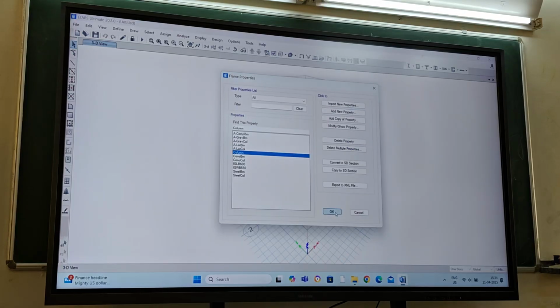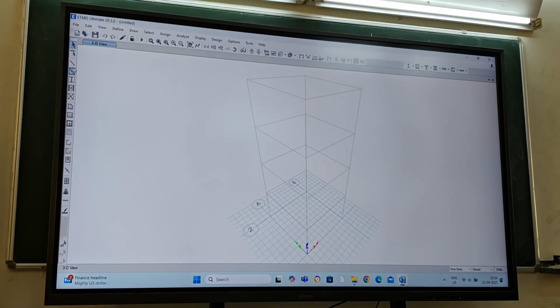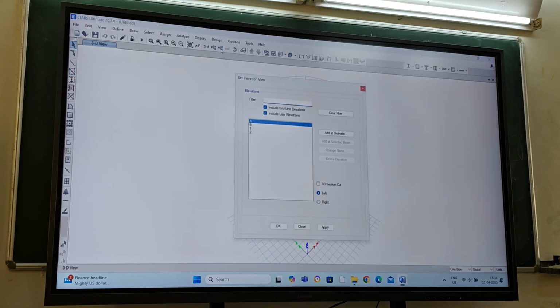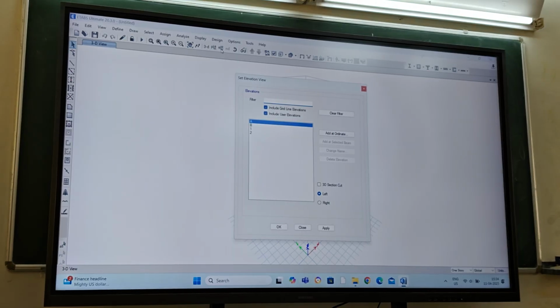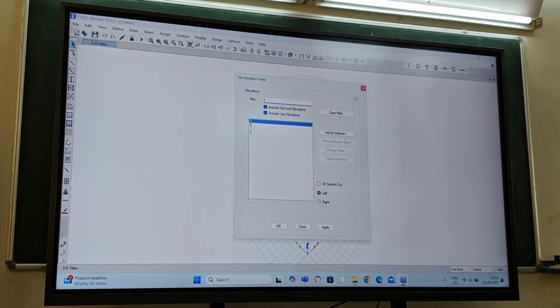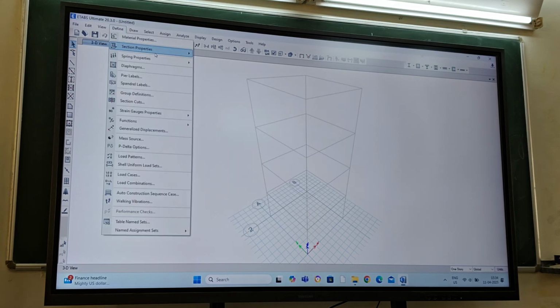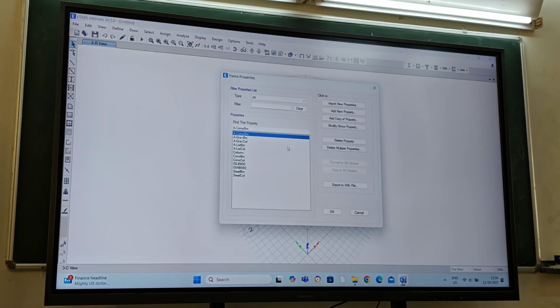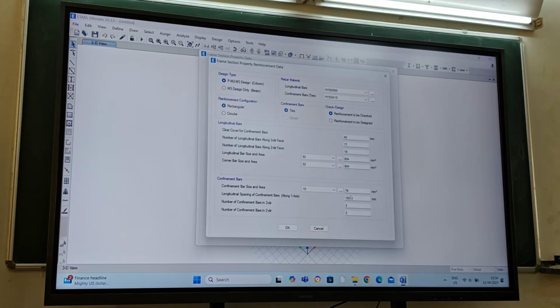So our section is done. Now we can draw it. So you need to check the confinement values. Confinement I have kept as Fe415. Okay, the rebar confinement you are talking about, not the material property but the number of confinements. This one, diameter, then spacing, all those things, right? So confinement will not affect our pushover analysis result. So you can ignore this.